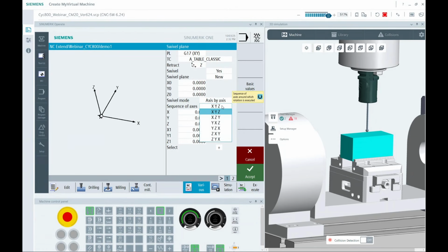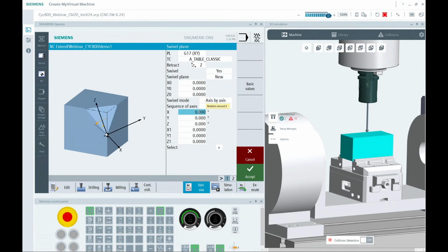Now, in a simple single rotary machine, there's usually not a lot of benefits to this because you're generally always going to plug the value in the X field. You may introduce a Z if you wanted to spin the coordinate system, but that would always have to happen after the X component. So you're really only going to use effectively these first two, what I say would be the most logical to choose. So I typically leave it at an X, Y, Z. And then I'm going to tell everything to go to 0. So I just want to make sure the table rotates to 0, no more shifts, and I don't need to worry about this little selector.